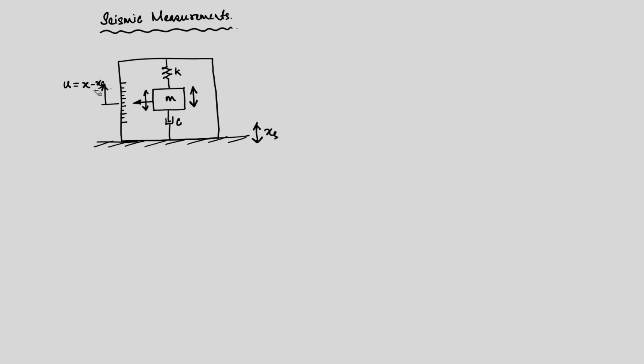We have already derived this expression for this quantity, and we will see in a minute how we can use that theory to measure the vibration. So, this is the schematic diagram of a seismic measuring instrument. Using this instrument, we can measure the displacement, also the acceleration. So, the ground displacement or acceleration, both we can measure depending upon the tuning of this instrument.